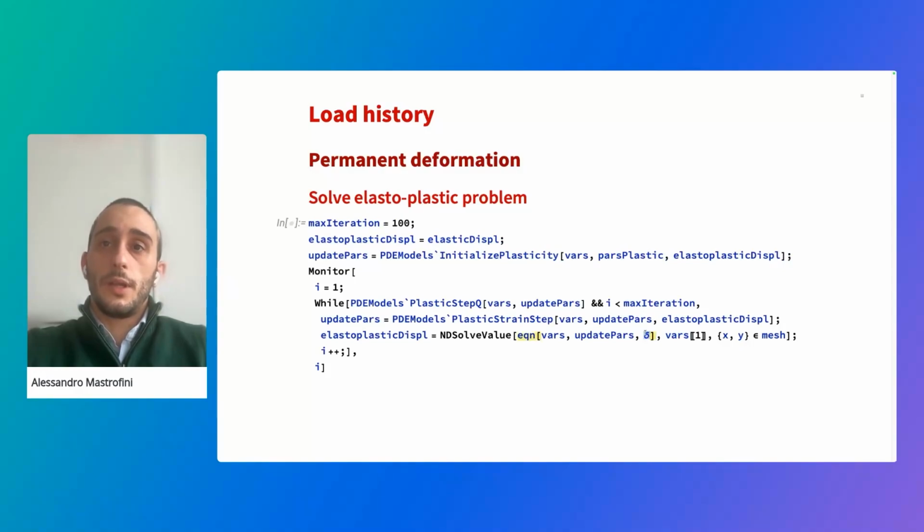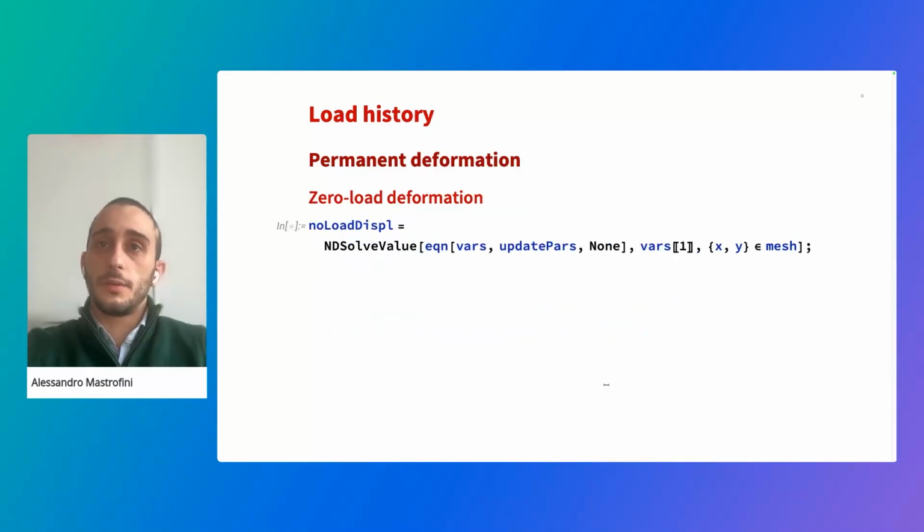Okay, so have a look here. The displacement is still delta, the imposed displacement, but we're going to perform another final step. So we solve the same problem with the same parameters. The update part here contains all the information about plasticity, basically the plastic strain and some other important variables for plasticity, but the equation is the same, but the applied displacement is now 0.